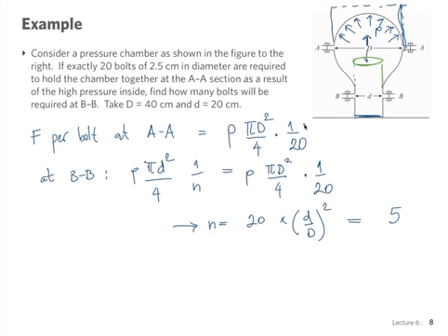You just apply the concept. We're looking at forces in that direction caused by the pressure on a curved surface. We just need to use the projected area. And again, like you said, the pressure is assumed constant throughout this tank. It's a pressurized tank of gas.